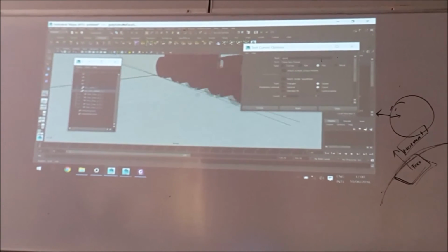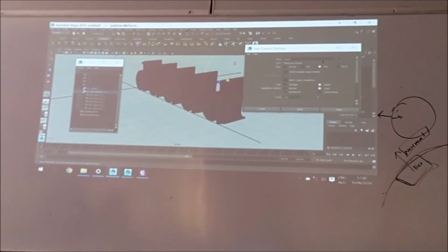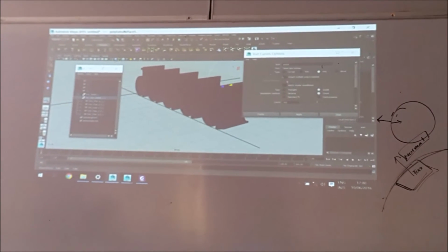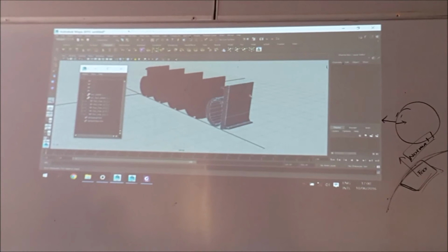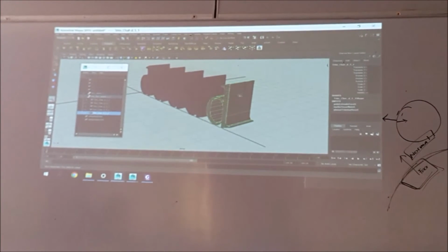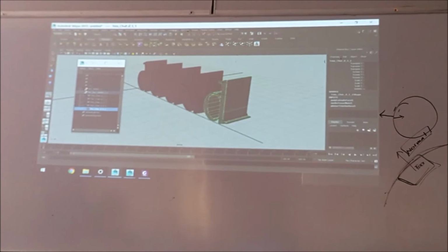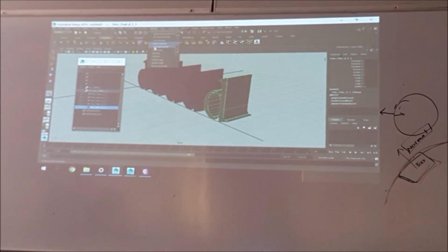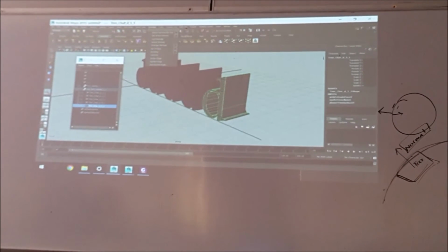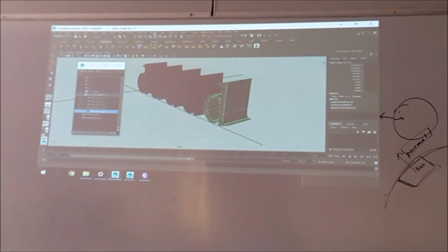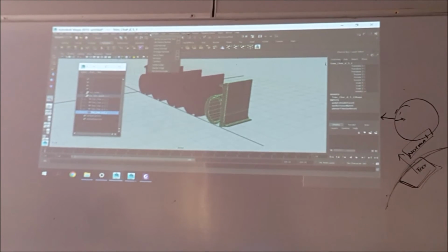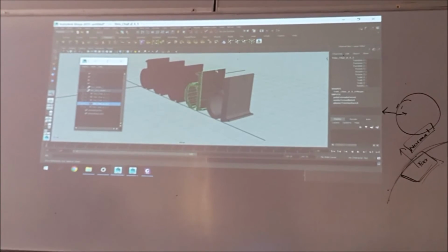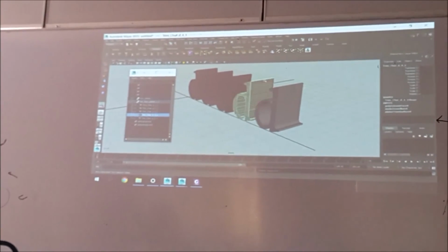Okay. This is a black color means normal reverse. This is normal correct. Let's say this has been reversed. You just need to go back to object mode. Then for reverse normal for polygons, it's under normal. Reverse. Polygon menu set, normal, under normal, reverse. If you want to repeat the last action, hit G.